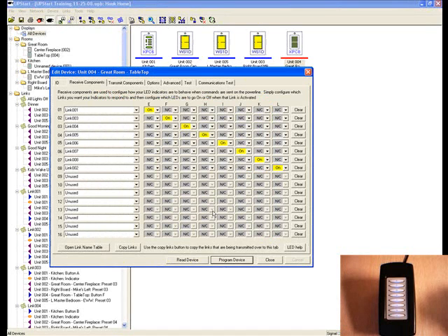Let's go to our keypad on the video, and I notice the E button is currently off. I'm going to press the E button. That's going to turn on the LED light, which then activates the scene. Now, because we're a super toggler, if I press this again, now that the LED light is on, it will turn off the LED light and deactivate the scene. You'll notice that the F, G, H, I buttons are set at no change. That means all these other buttons, if they happen to be activated, they will not turn off.